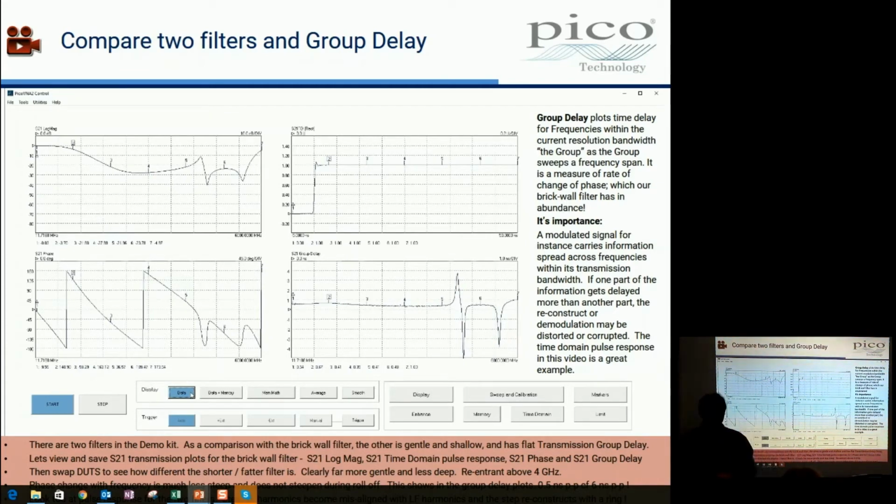And you may remember the other day I said how important it was that for a communication signal going through a filter, you'd better not change the delay of one part of the modulated signal relative to another part, otherwise the timing of the data is all going to be screwed up, and it'll be corrupt even when you do see it again.